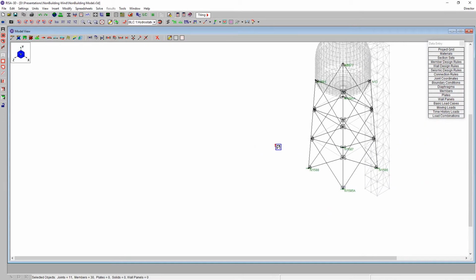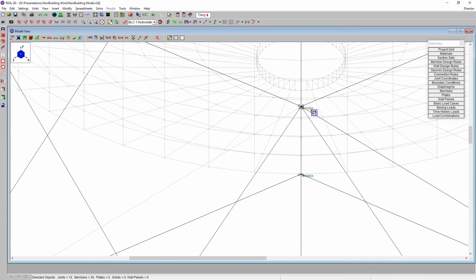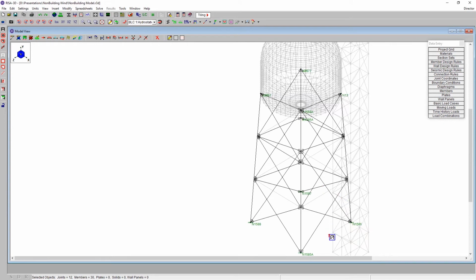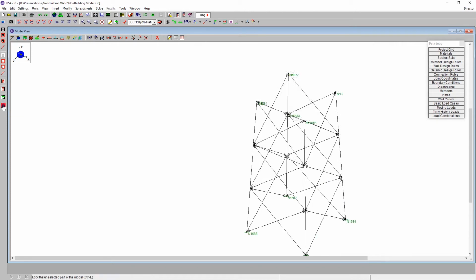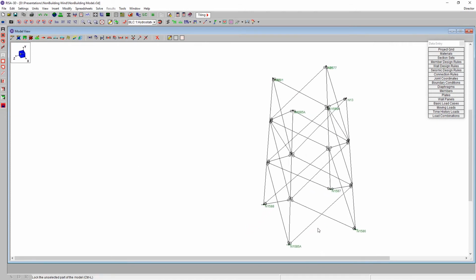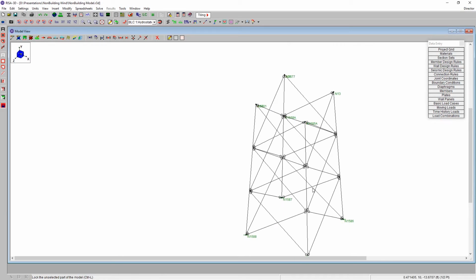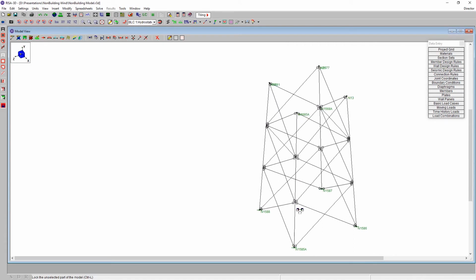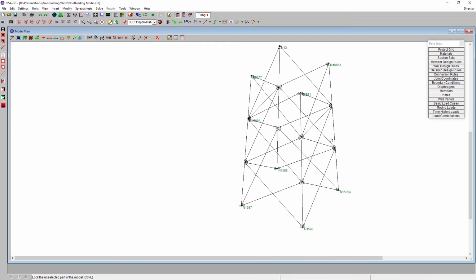So now coming back into an isometric view here, let me make sure that I have all the nodes selected that I'm going to need, and that looks like a sufficient amount of snap points. Now what I'm going to do is use this tool on the left here, this padlock tool, to lock everything else out, so that now we are only taking a look at the tank legs. And what we know from our wind load calculations already is that the tank legs need to experience a pressure of 52 psf. And I'm going to have that always act in the positive direction.